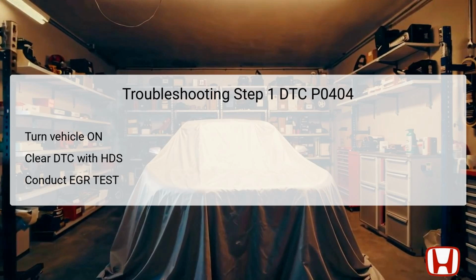If the EGR test indicates that the system is functioning properly, this suggests an intermittent problem, and cleaning carbon buildup on the EGR valve might resolve it. Otherwise, follow the next steps. Moving to the second troubleshooting step, turn the vehicle to the off/lock mode. It is crucial to ensure that the vehicle is completely powered down to avoid any electrical damage.